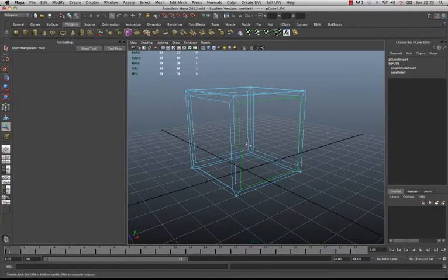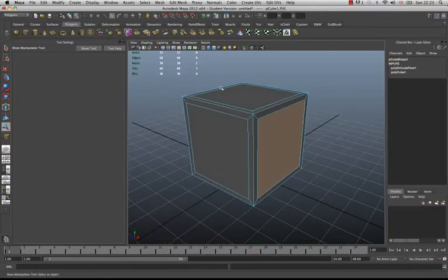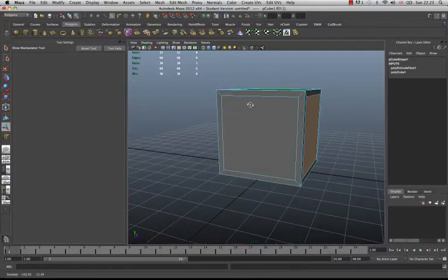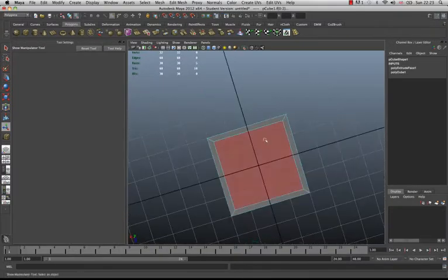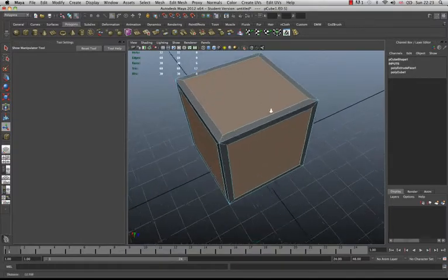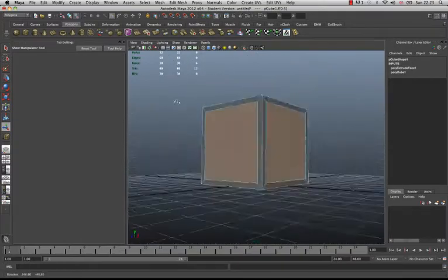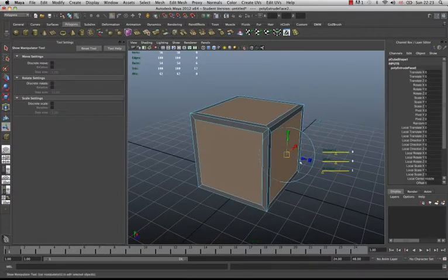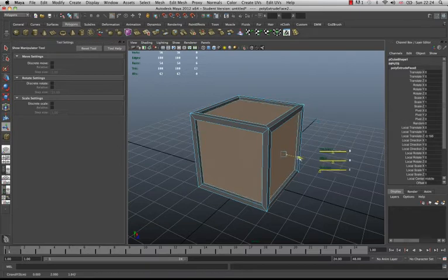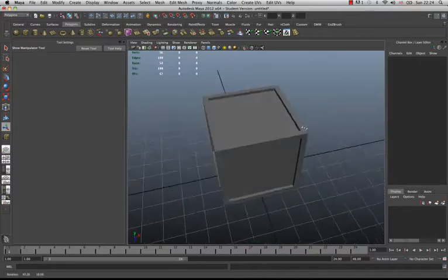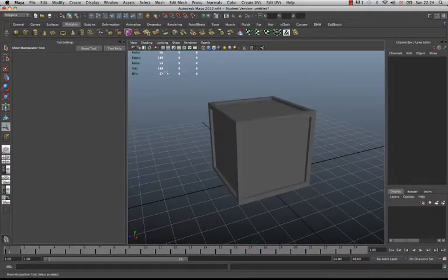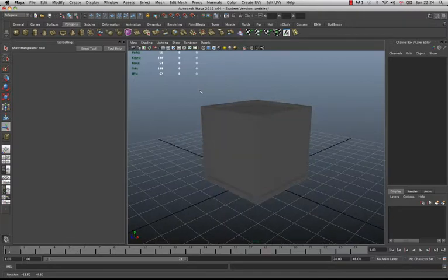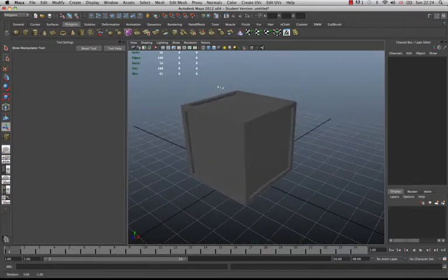Next thing I want to do is just select the faces. I'm going to go to shaded mode. This is using OpenGL shading. This is just going to colour in all those faces based on where the camera is and where the world light is. So if I'm all selected, I'm going to press the extrude button again. This time I'm just going to move the actual face back against its surface normal, just to create a little indentation. Okay, so there we have it. There's our ammo crate, and we have 108 triangles. So that's not bad. It's a good look.